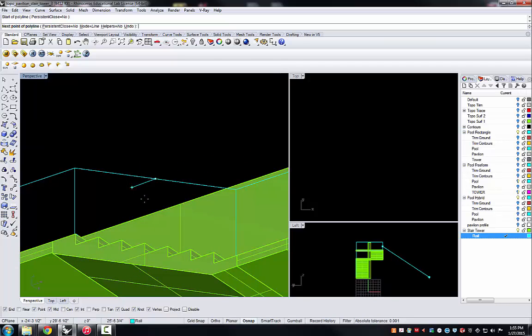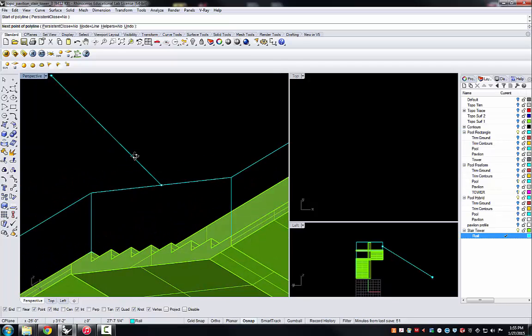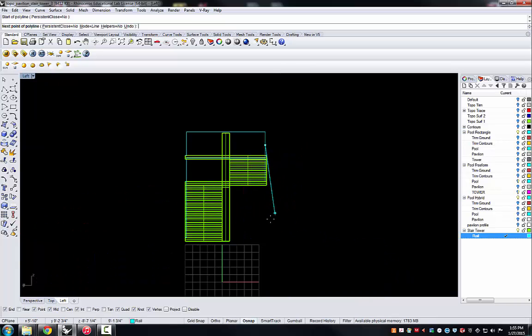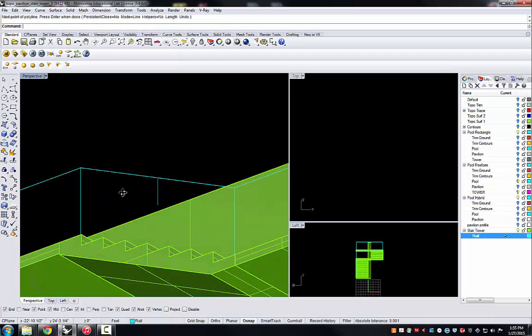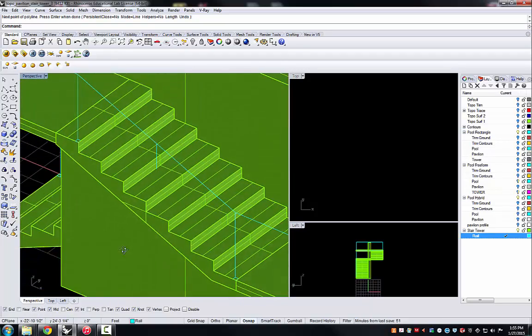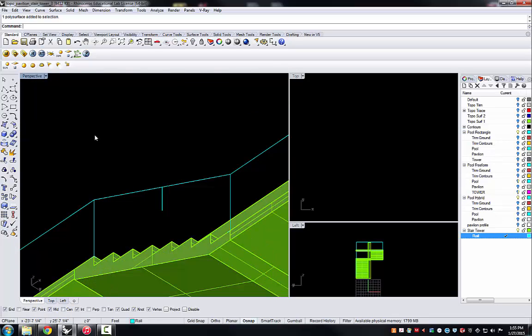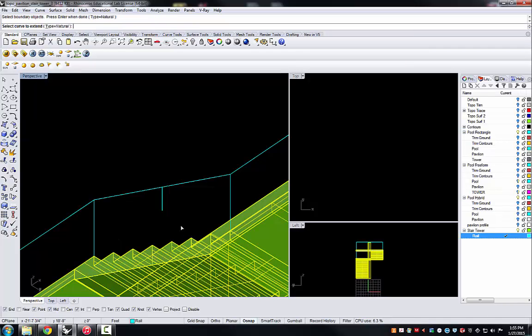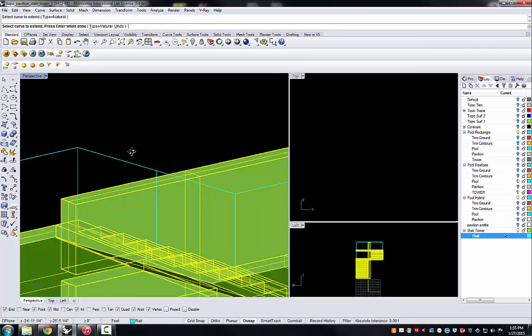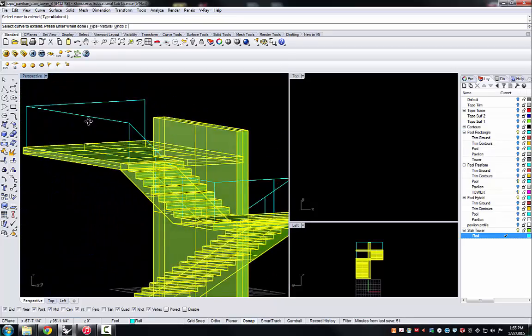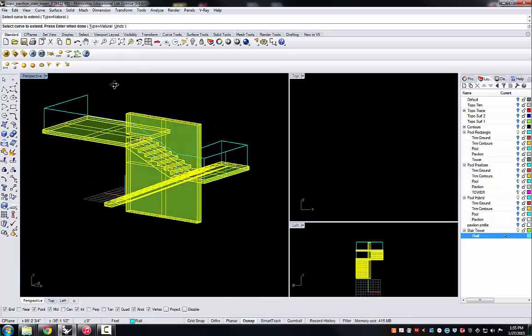But for this vertical part, I can select the midpoint of this upward sloping handrail. Again, go to an orthogonal view where I can extend it downward using Shift, and come back and I'll see that I have that. It needs to be extended downward to come down and touch the stairs themselves. So I'll again use my extend command and select the stair as the boundary and this curve as the thing to be extended down. And I'll go around and do that around the edges of this.